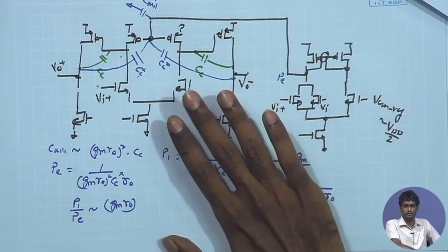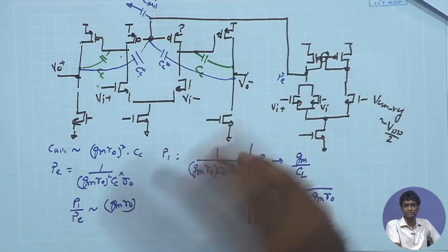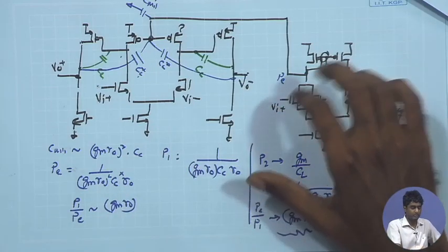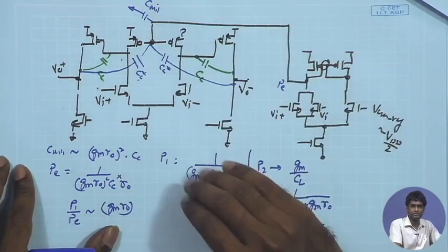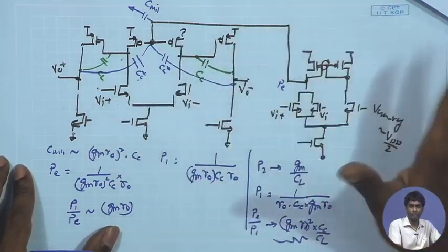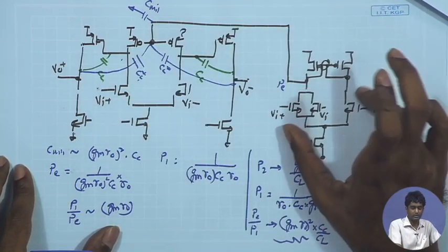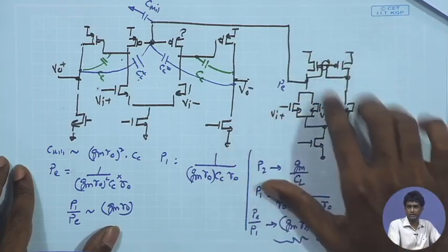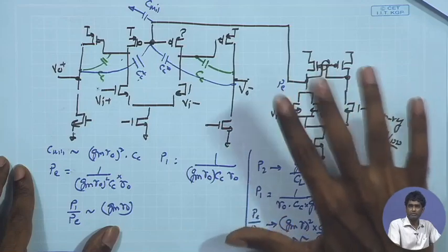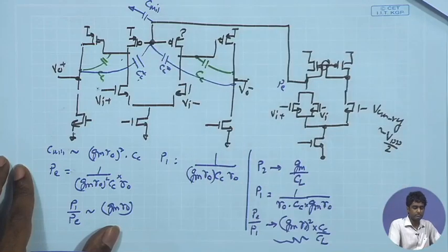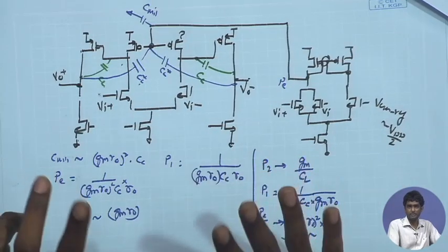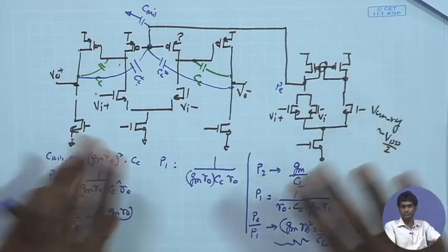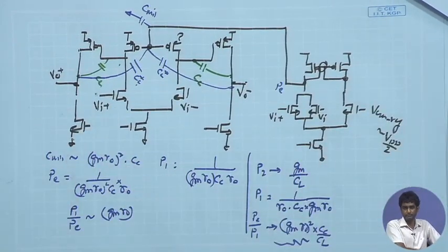So even if that's not a good choice in some condition, in some other conditions it may become a good choice where possibly your area constraint is smaller and you want to have common mode having much lesser current, so that the gain of the stage is large and you are having a large RO anyway. So in those cases you may end up using it. So if you are simulating it and trying to see what is the disadvantage, you should be at least aware of this trade-off.